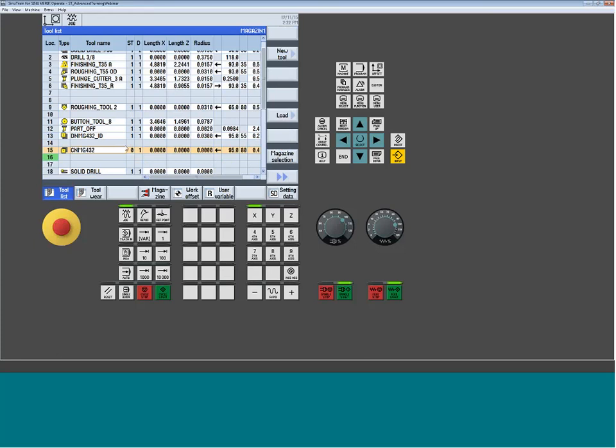432. Now, a 432 insert could exist in my OD, ID, and it's common to have ID. Remember, this portion is only just the insert. So a lot of times I will tell it maybe it's an OD tool. Maybe I even want to tell it it's a right-hand or a left-hand tool. I could put that as well, depending on how involved I'm getting into different orientations of tools. And you guys will kind of come up with what you feel like your own standard would be. So we give it a name.